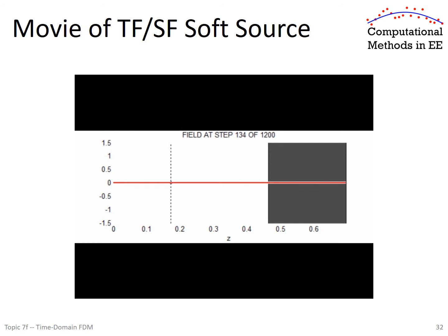Then a specific case of the soft source is the one-way source. And I use the total field scattered field technique to implement that one-way source. It's a soft source, so when power reflects off our device, we inject this one-way wave. When power reflects off something, when it goes back, it's able to pass through that region where we injected the source. If that were a hard source, that would not be the case. The one-way source also gives us the ability to better control the amplitude of the field that we're injecting. And it doesn't send any energy backward that would hit that left boundary.